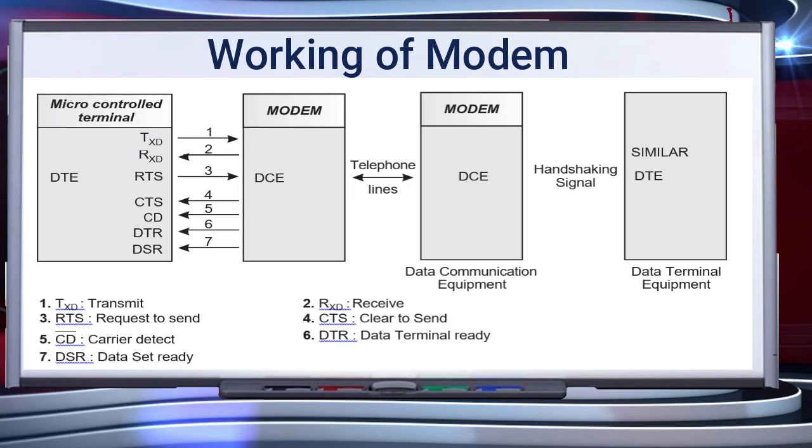The terminal then sends serial data characters to the modem. When the terminal has sent all the characters, it makes its RTS signal high, which causes the modem to unassert its CTS signal and stop transmitting. Similar handshakes occur when the modem and computer are on the other side also.